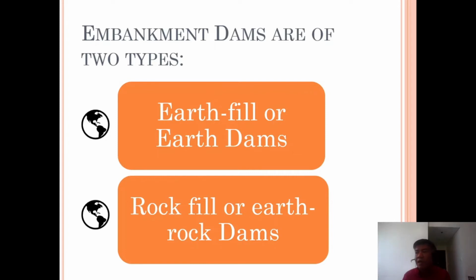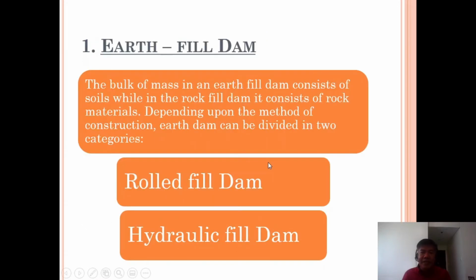For rock fill, of course, it is made of granular materials, so the pores are much bigger compared to that of the earth fill. Compacting it is not that easy because there are still voids. So what you're going to do is mix it with earth fill to fill in the voids. Those are just examples. Later you can have it analyzed using software or some theoretical analysis.